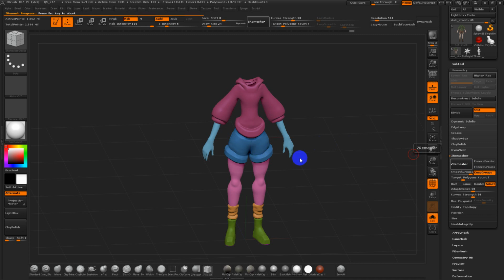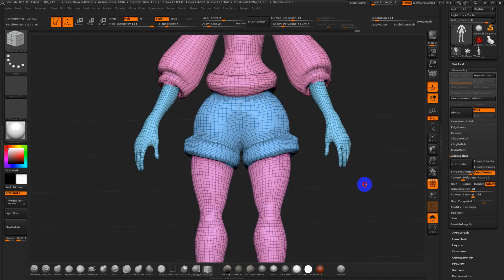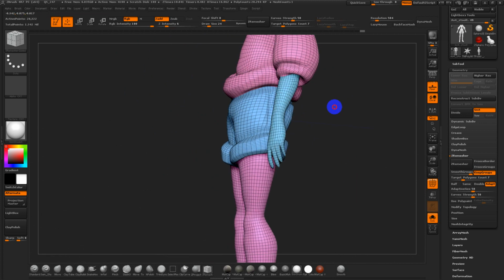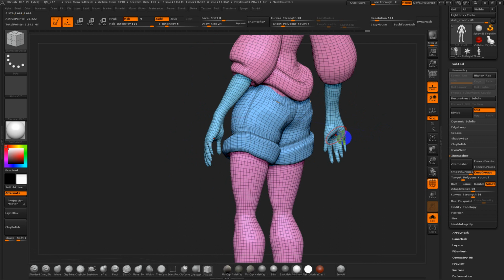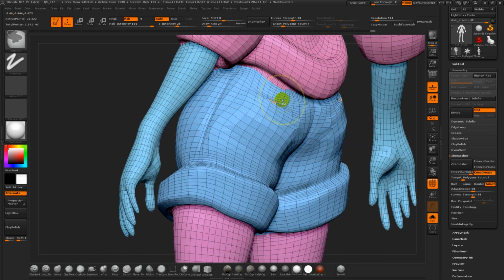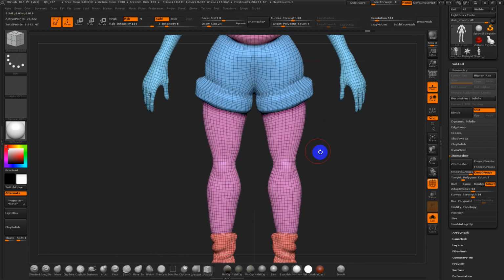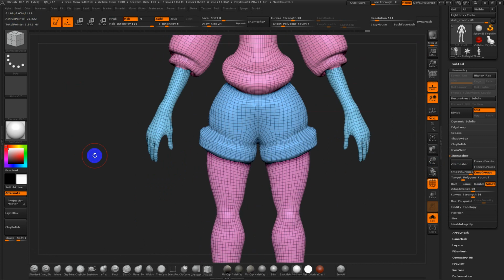Okay, so now, what's great about this is you get much cleaner lines along the gap areas in the clothing. It looks like we've got a stray polygroup in here, so I'll have to maybe undo and fix that. But for the most part, the topology generally flows much, much better through the legs. Again, I set it at 7,000 with adapt on, and it went to 20.